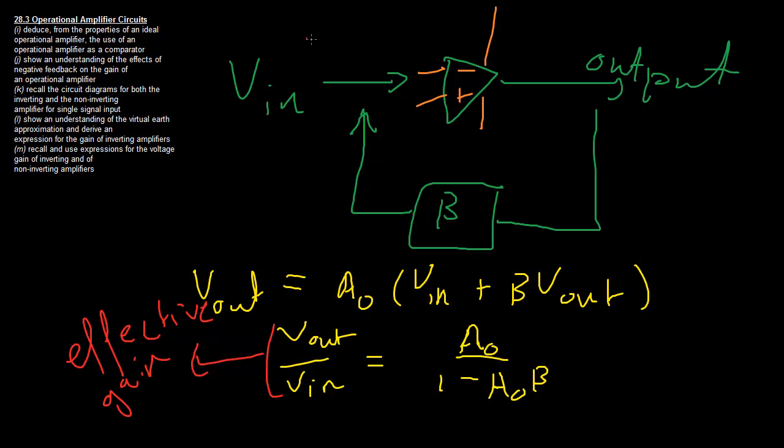If I put 5 volts in, and this operational amplifier has a physical characteristic of multiplying by 10, and let's just say the power supply is infinite for our argument, if I didn't have this feedback loop, with a 10 times multiplier my output would be 50 volts.